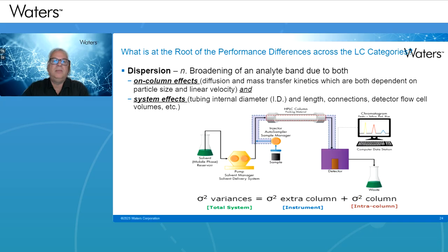The peak becomes a little bit larger. In the tubing, when it arrives at the column, I want to have the narrowest band possible. If we start to dilute, we start to have a larger band. Now in a gradient, I understand we will refocus at the end of the column, but this is still contributing to the dilution, certainly after the column to the detector.